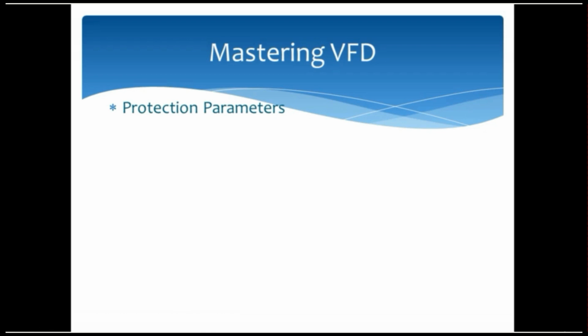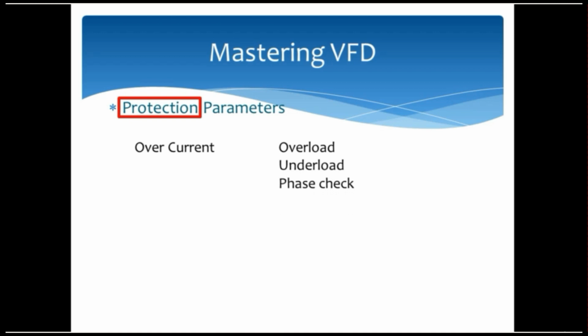One job of VFD is to protect the motor. It has a lot of functions to protect. Some are built in like overcurrent, but some are required to be enabled or need some configuration to suit our application like overload protection or underload protection or input and output phase protection.